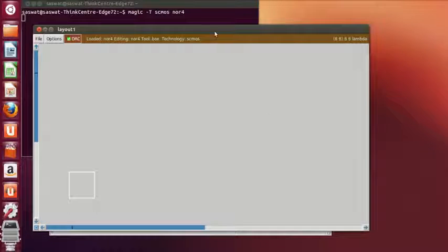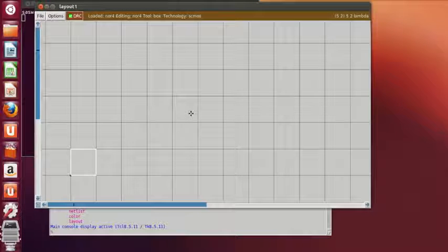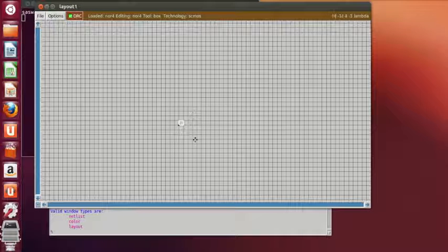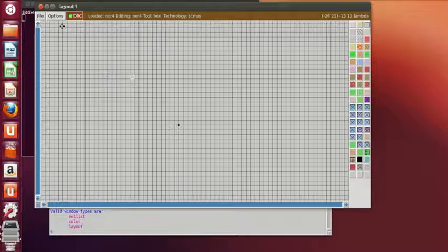Okay. Now if I want the grid, then I'll type G on my keyboard. Now Shift Z. Okay, this is the zoomed out window. Then go to options and then the toolbar. So here are my nwell, pwell and select, P-select, ND contact, PD contact, P substrate, N substrate.